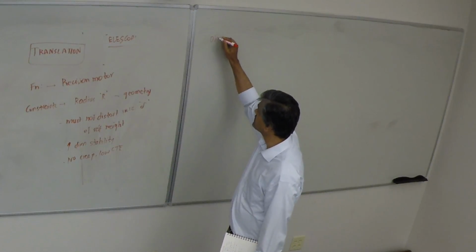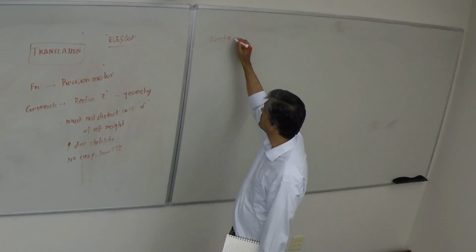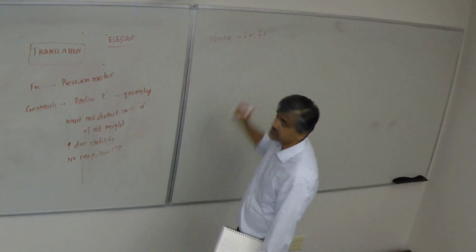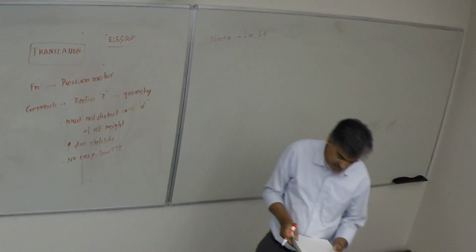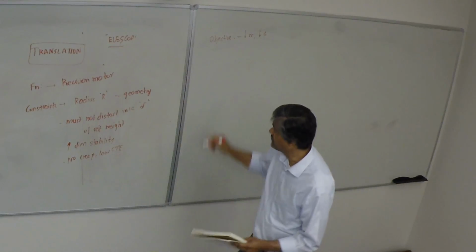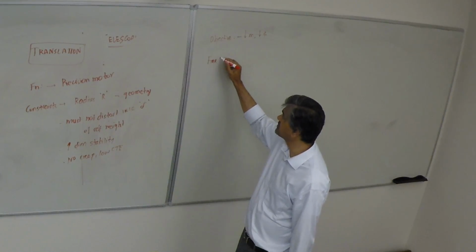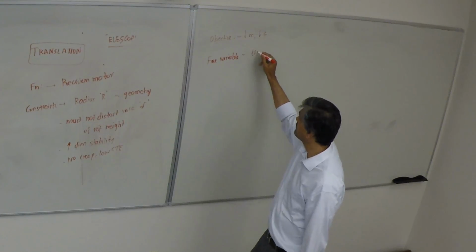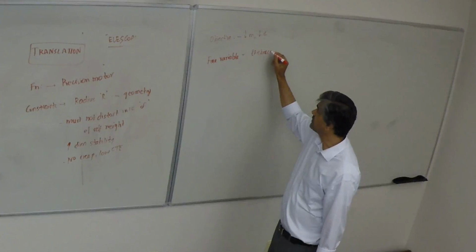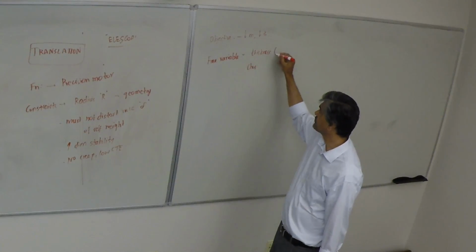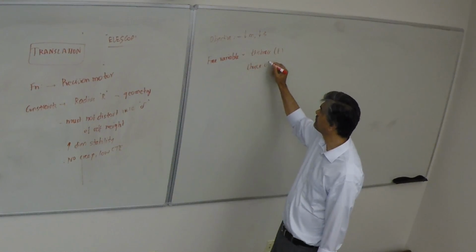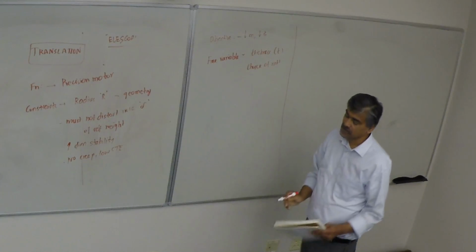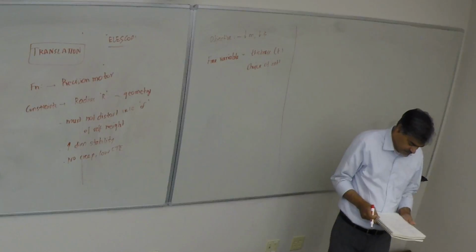So the objectives in this case would be to what? Minimize mass and minimize cost, right? You want to minimize both as such. And what would be your free variables? It would be your thickness and choice of material. So you have a couple of options there.